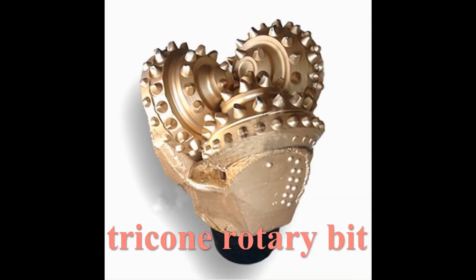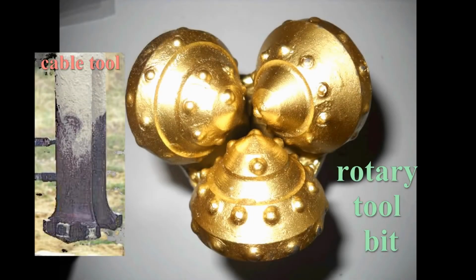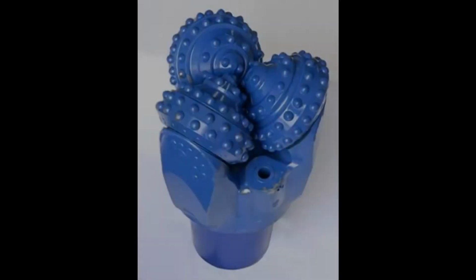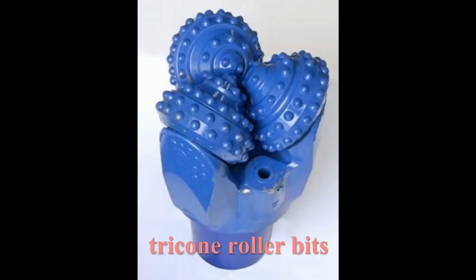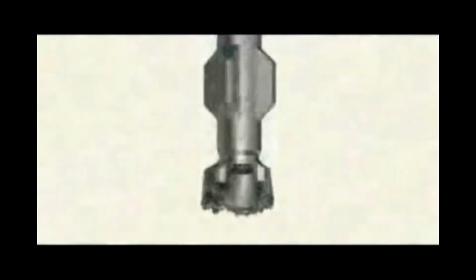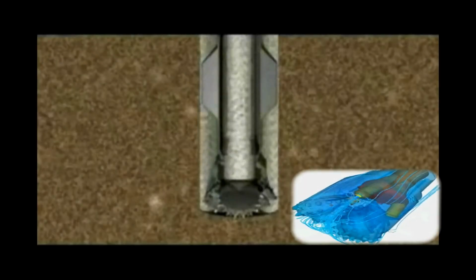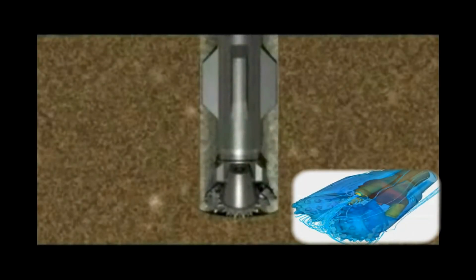Let's examine the rotary drill bit to better understand why it quickly replaced the cable tool drill bit. Tricone roller bits are the most commonly used bits. A clockwork rotation of the drill string causes the 3 roller cones to also rotate, bringing successive teeth to grind vertically at the bottom of the hole. With the weight concentrating at the point of the teeth, the rotating bit crushes the rock. The debris from these cuttings are then swept away by the mud jetting out of the 3 downward-facing nozzles.